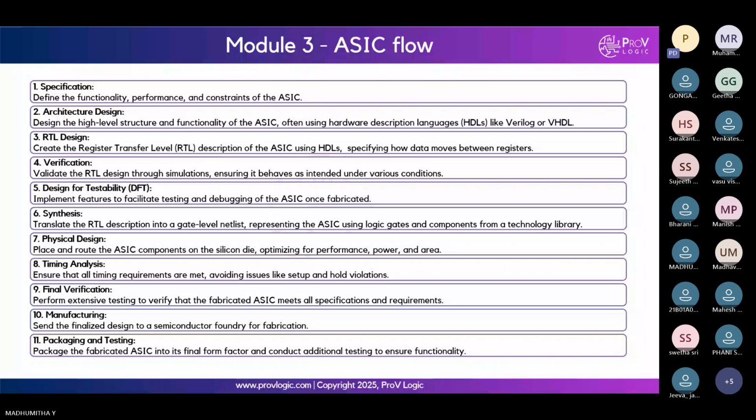But in sign off, the advantage we have is that even if we see a bug that was missed during the placement stage, and we still proceeded to routing, which is the final design stage, you can still go back and fix that bug alone. That is why it is called engineering change order. You can change the order of the flow and fix the bug. In sign off, only fixing will be done. You cannot redo the entire design during sign off.